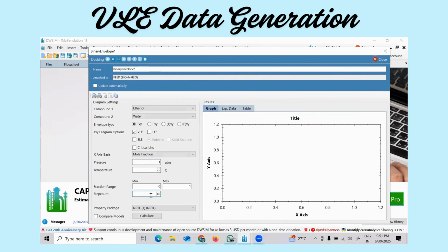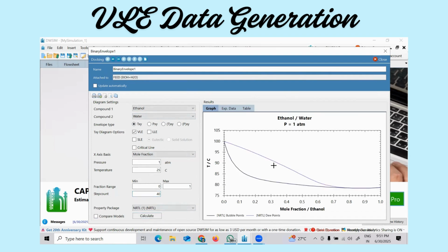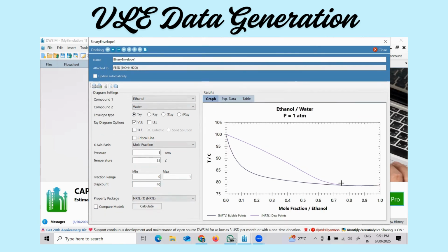For a smooth curve, step count is very, very important. If I take very less step count, the curve will not be smooth. So if I do this, then what do I do? You can see at the bottom left-hand side, there is calculate. I say calculate, and it has given me one TXY diagram, which shows it is an azeotropic composition. Okay, but it's very narrow. You can see, it's very narrow here. But to find where the two compositions are the same, that is the challenge here.